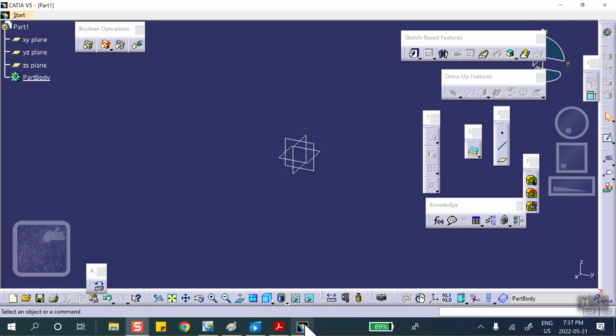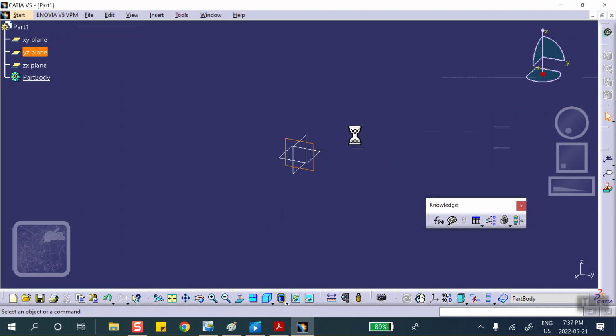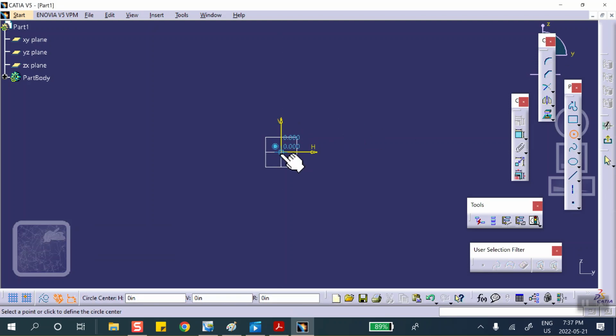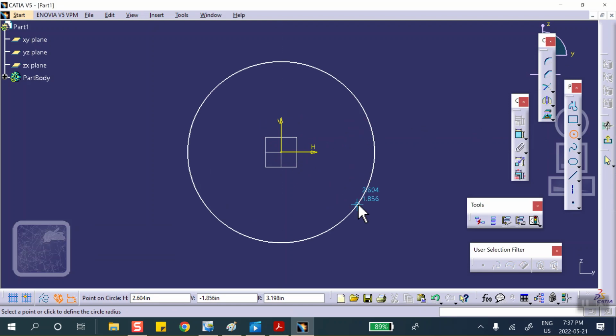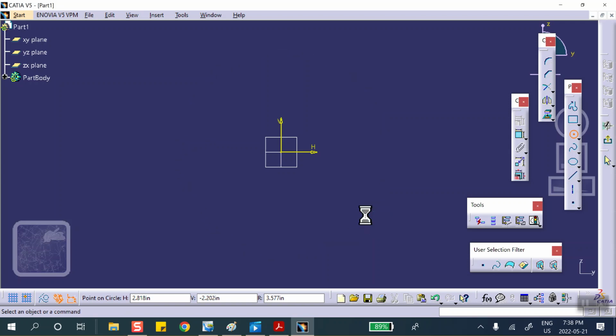So let's go ahead and create this geometry. On that plane I'm going to sketch a circle of radius 10. That's the radius of that loop. So let me draw a circle here. Now we have two choices. We can draw the circle and cut it, or we can do only half of the circle, and that's exactly what I'm going to do. So let me escape this.